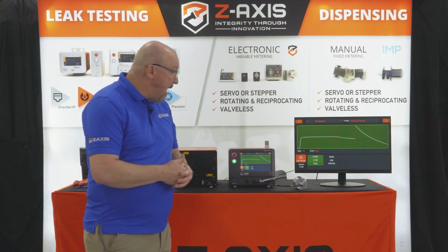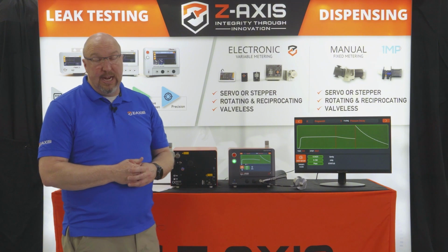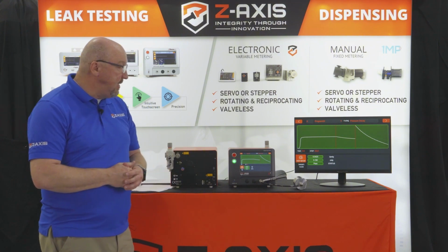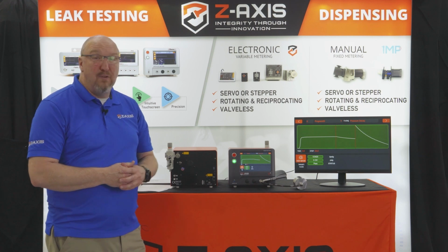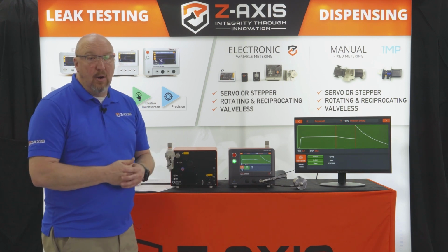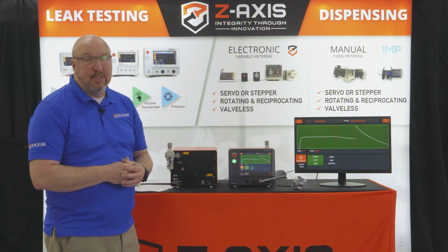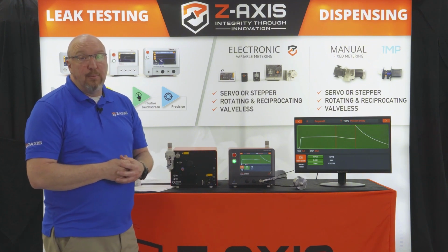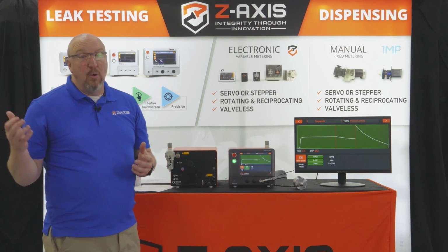In this case, we had 0.033 for a good test, and when we added the leak standard to it, now we get a 0.042. So that wouldn't follow our rule of thumb. It doesn't have 3 times the separation. If I have a 0.03 on a good part, I want a failing part to be 0.09.